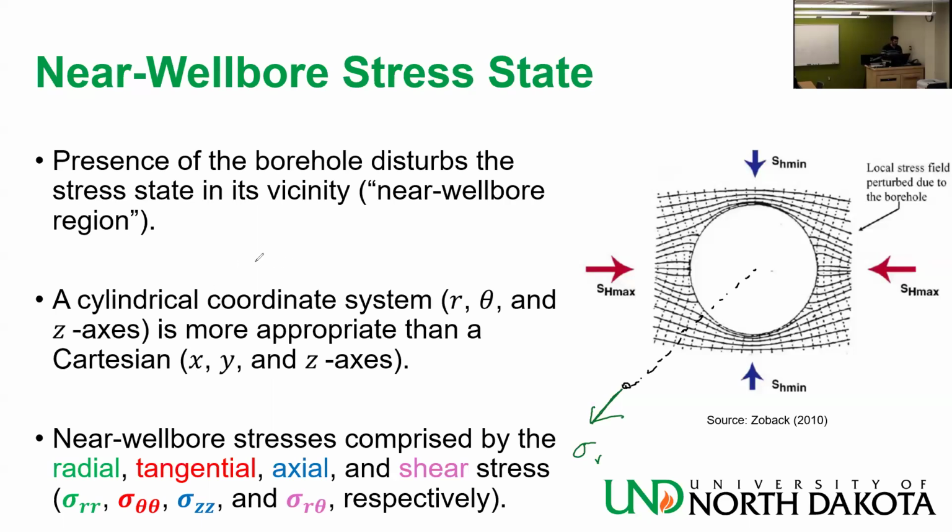Because now I'm gonna come perpendicular to the radial stress, draw another arrow like this at right angles. Put the arrows like this again in tension, and I will call this sigma theta theta, the tangential stress, also known as hoop stress. Hoop stress is a nickname. Circumferential stress is another name. Tangential stress is the official name.